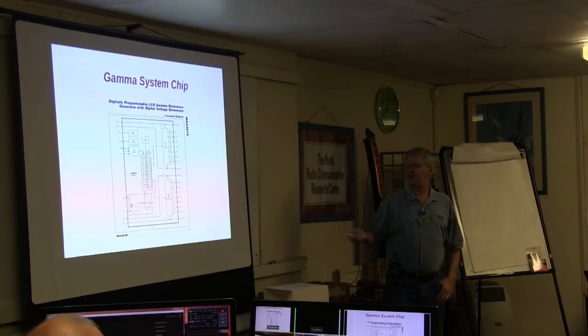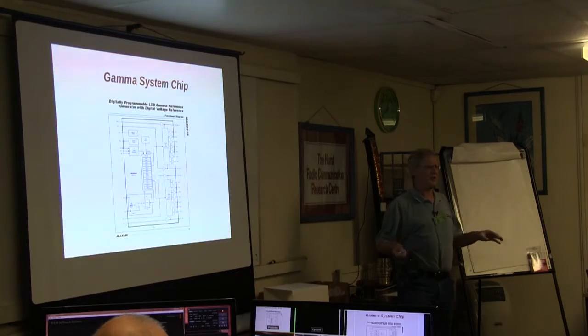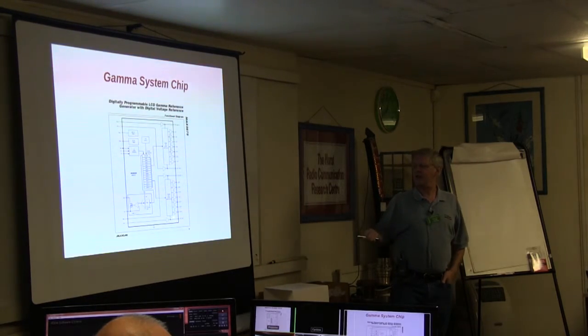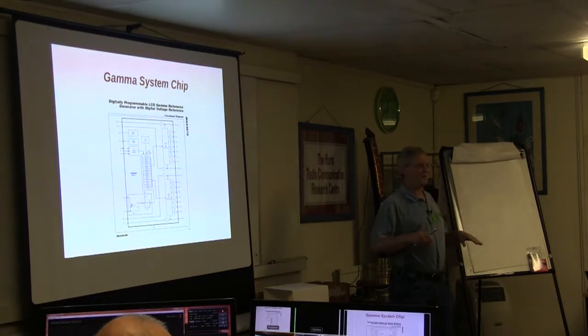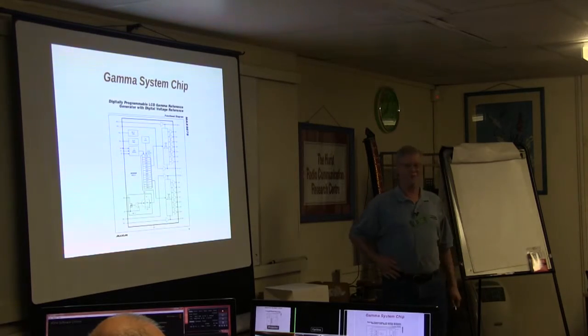So that was one of the challenges as well, by the way, that now we need about 16 volt range on here, and 16 volts is kind of the limit of one of the silicon processes, and the next step up is 22, 23 volts. So it kind of set it at that, because as you go up in voltage, the number of layers you need in the IC goes up and the cost goes up. They don't want to pay anything for this stuff to put in these TVs.